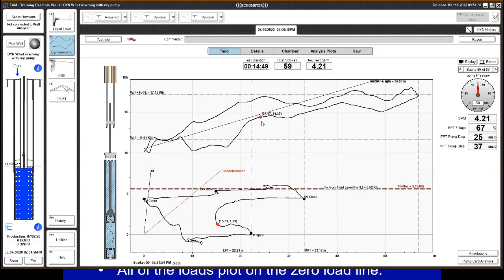Well, common question. I have a rod pump controller in my field, maybe a SAM controller, a Lufkin controller, or a different type of controller. I can pull the data in my SCADA system, or I can download it somehow. Can I analyze the data using the Echometer system? Well, there is no compatibility between the systems. First, the data that's being input from those controllers has a much lower resolution than what we handle.